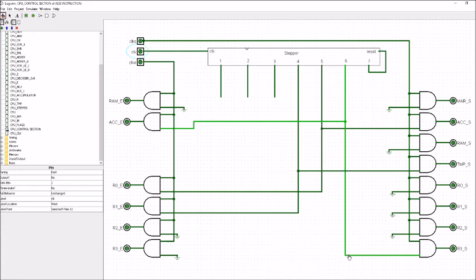And then we're going to place that information into register R3, so it means that register R3 will then be set, but of course these won't happen until we go through the set and enable for the clock pulses. So the enable goes high, and the accumulator is enabled, and then the set goes high, and register R3 is set, so we take the information on the bus and put it into R3. The set goes low, so it's stored in R3, and then the enable goes low, and that's us finished.